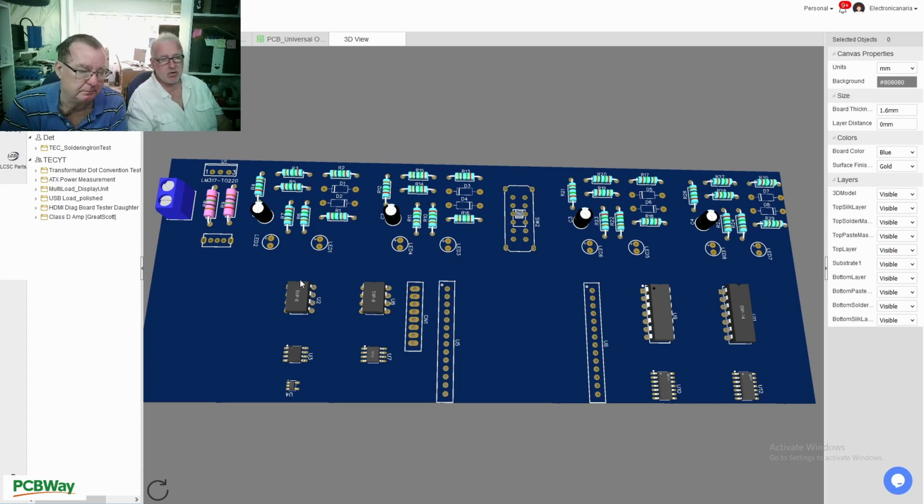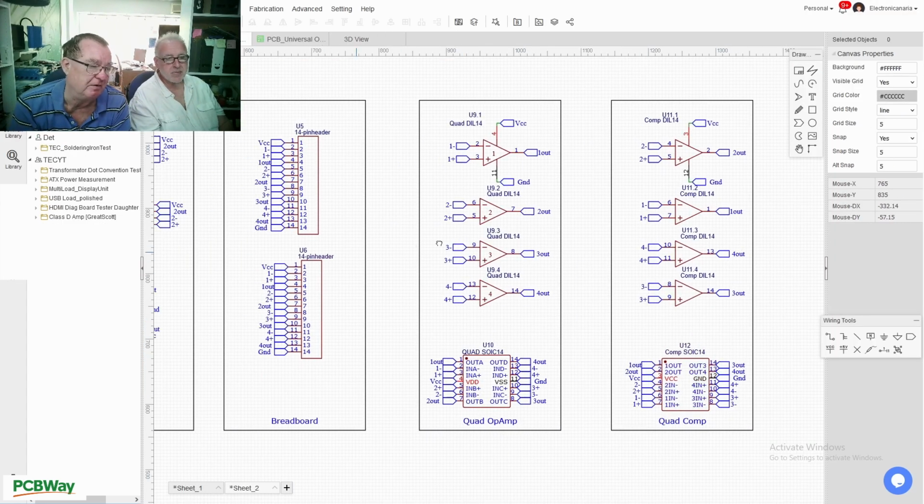So this will be called single, dual, and with all the naming schemes you already saw on the layout. And our little breadboard that you see here sits in between these two rows of pin headers. Well, not really pin headers, they're like little sockets for DuPont leads. So we can just stick this onto the middle of our PCB here. And if you have some device that doesn't match the standard pinouts we've used, you can literally just connect the leads to where you want.